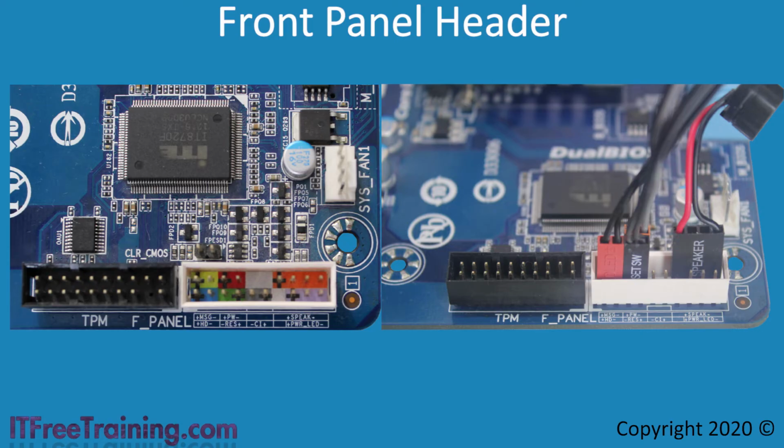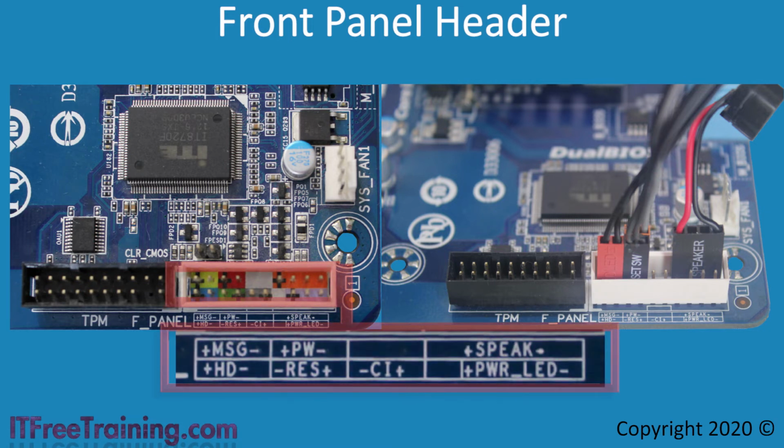To determine which connectors are connected where, most motherboards will have writing next to the header. It is quite small and difficult to read. Otherwise, you can find the information in the manual. For connectors like switches, it does not matter which way they are plugged in. However, lights and the PC speaker need to be plugged in the correct way.